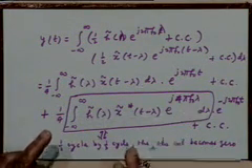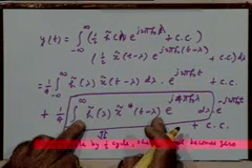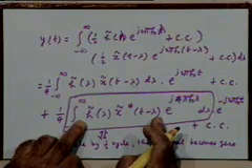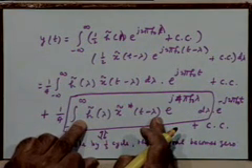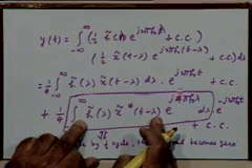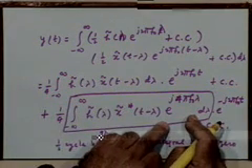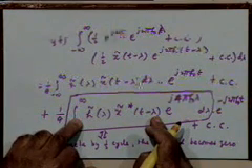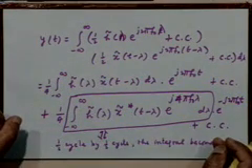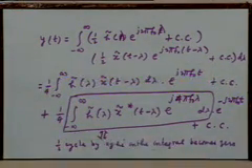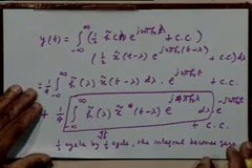The argument is simply this, that the integrand is a product of two functions. This part of the function is a low pass function and fluctuates very slowly. We are assuming here slowly enough so that over one cycle of this it remains more or less constant, and therefore over one cycle the integral is 0. Repeat the argument for every cycle and therefore the integral becomes 0. Okay.